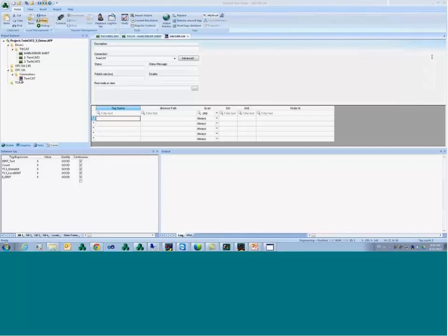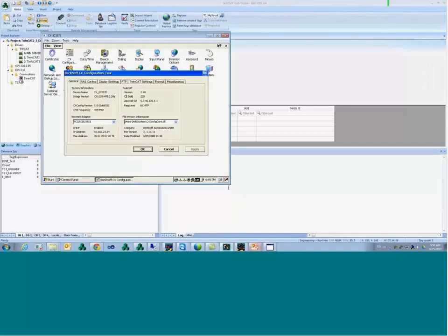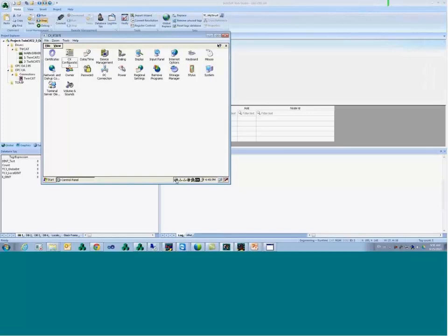So I got a question here on how to host the InduSoft thin client on a Windows CE Beckhoff device. If you want to have a thin client there, the easiest way to host anything there is this. You don't even have to have a license for that. You just copy the CE server program to your Beckhoff device. So it's this one here, remote agent.